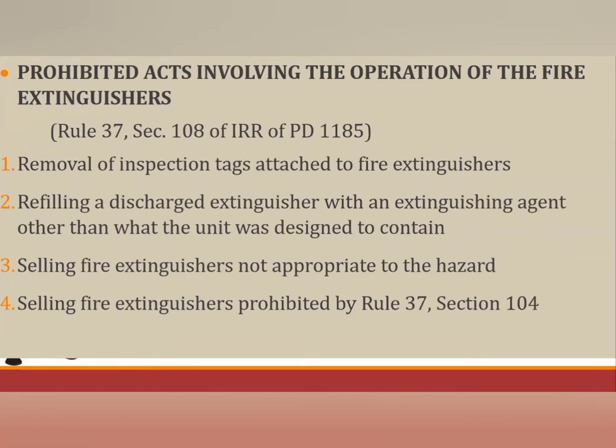Next, prohibited acts involving the operation of the fire extinguisher, which are also stated in Rule 37, Section 108 of PD 1185. It states the removal of inspection tags attached to fire extinguishers. Do not let yourself do that, or when you notice that the inspection tags are detached, you may report or call the attention of the manager or the owner of the store.